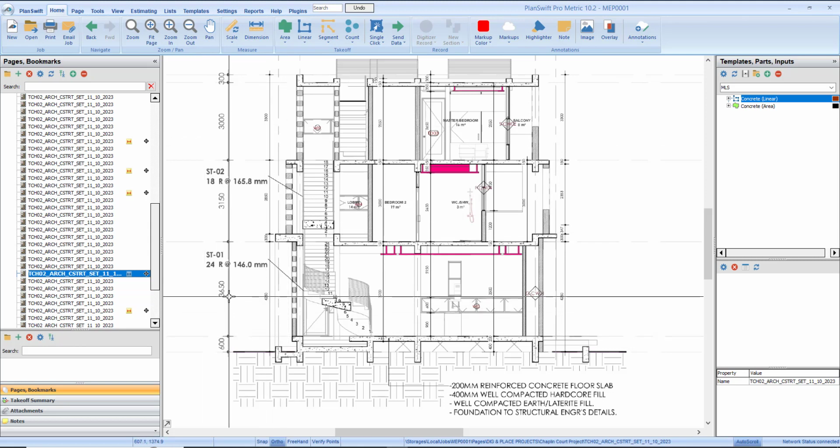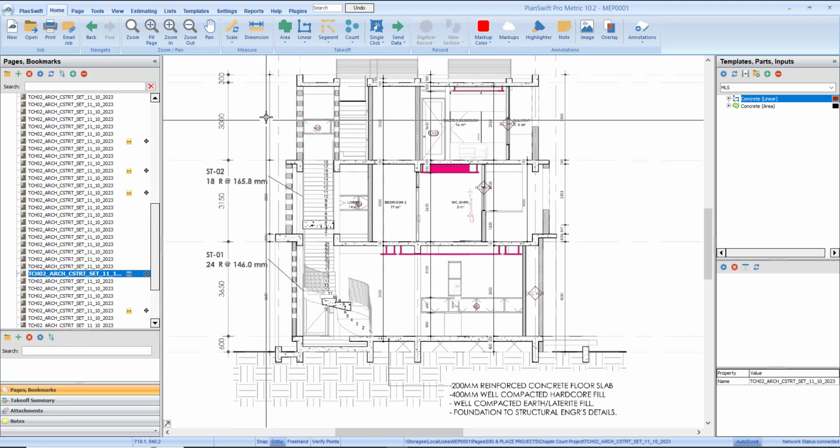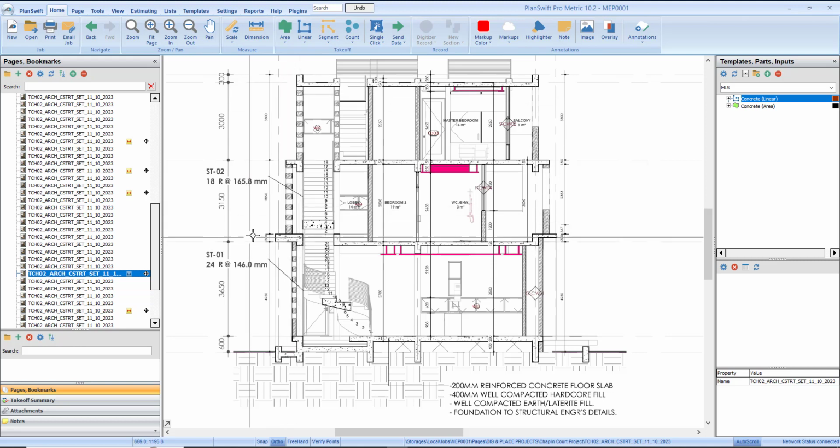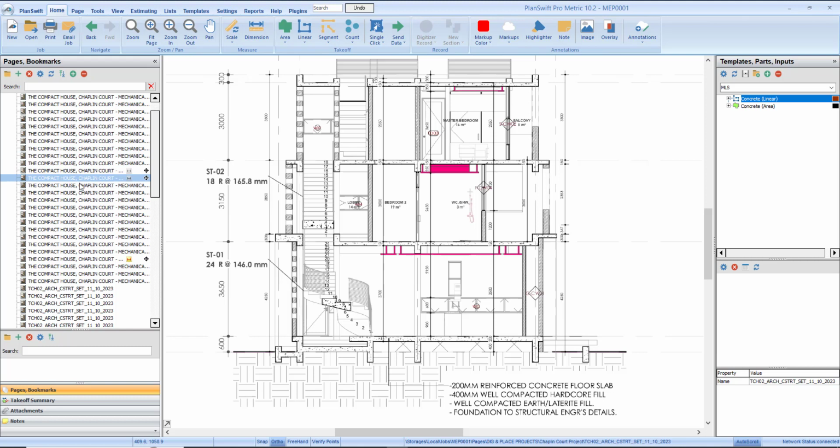This height is 3650, while this other floor is 3150. So you don't assume the last floor is around 3000 millimeter. What this sectional drawing helps you to do is so that you don't assume any figure. Of course, you have to use this drawing to be able to determine the height of each of these pipes. Okay, so let me go back to our drawing where we want to take measurement.